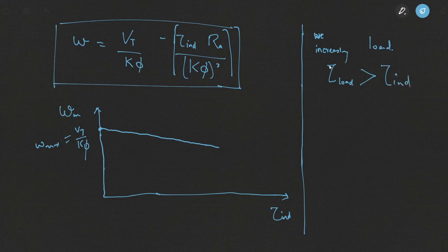Fine. So this is your load that's actually applied to the shaft of the DC motor. This torque is basically applicable to the shaft of the DC motor. This is the electromagnetic torque that's actually induced in the DC machine because of the electrical and magnetic principles. That torque is simply called K phi into IA. So once this happens, torque load is greater than the induced torque in the machine. That means naturally the response is that speed decreases.